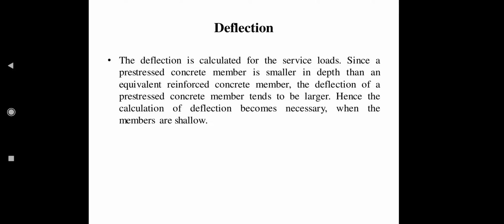Since a prestressed concrete member is smaller in depth than an equivalent reinforced concrete member, the deflection of prestressed concrete members tends to be larger. Hence, the calculation of deflection becomes necessary when the members are shallow. The calculation of deflection for prestressed members is mandatory because if we consider the thickness or cross-section area of prestressed concrete members and reinforced concrete members, we will see that the cross-section area of PSC members is less.